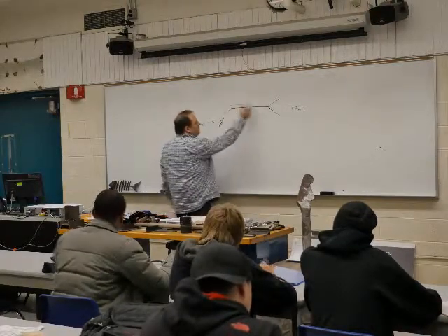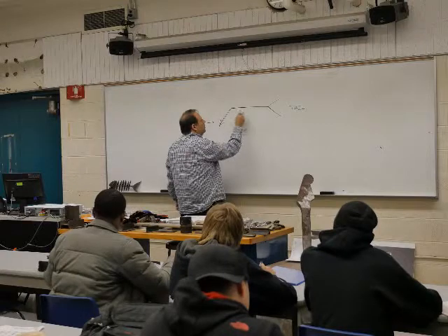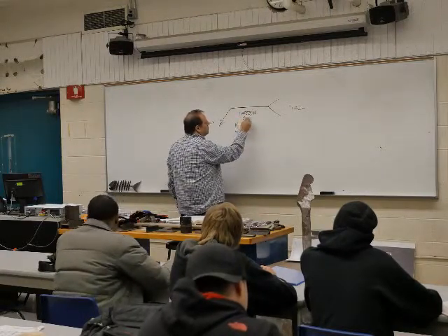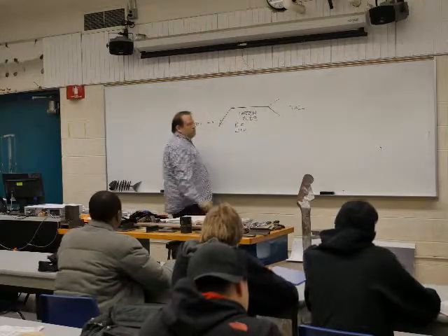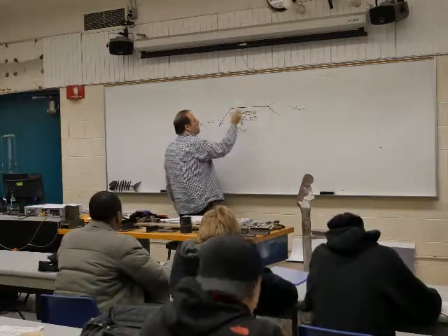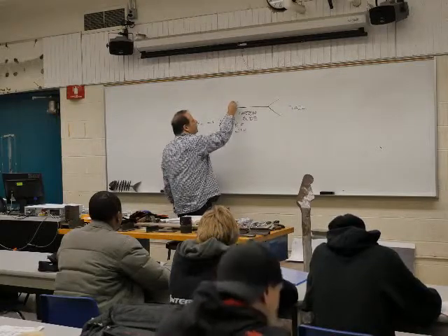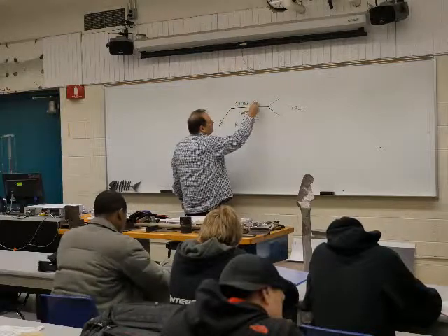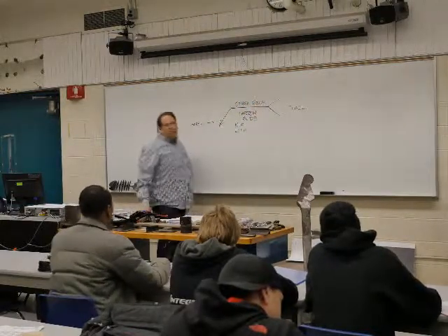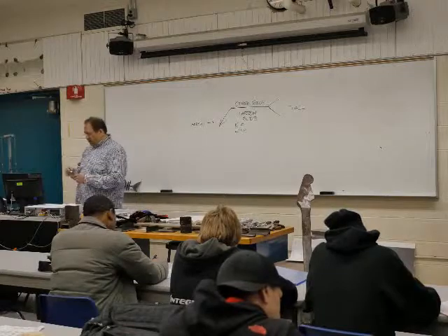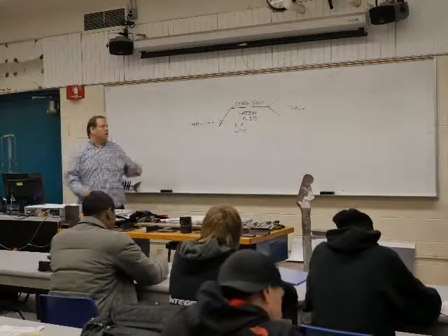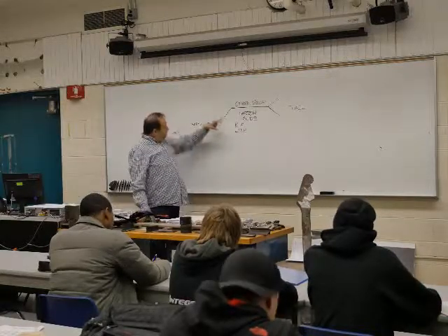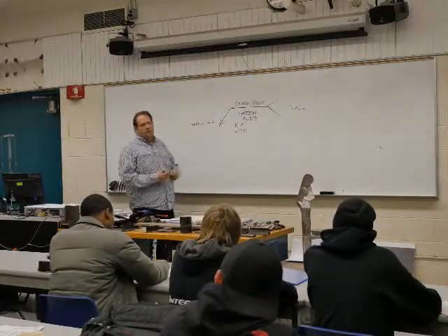So we're going to say that any information here is going to be on the arrow side, and any information that ends up on top of the reference line is going to be referred to as the other side. So if the information is below, it's going to be really where that arrow is pointing, but if it's going to be on the other side, it's basically the other side of the weld.